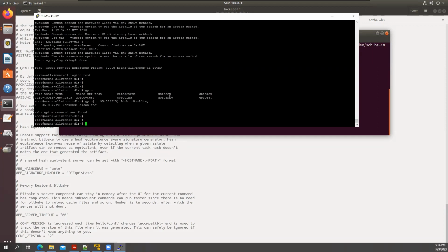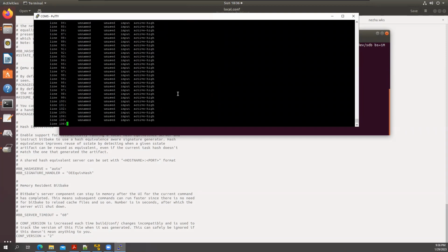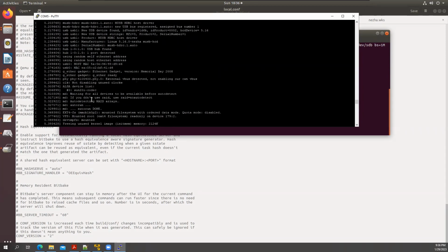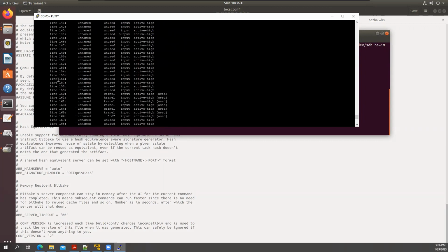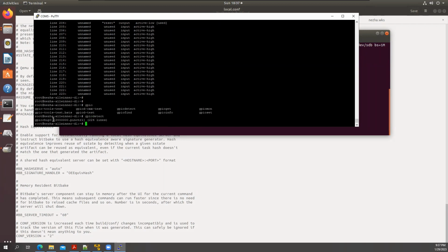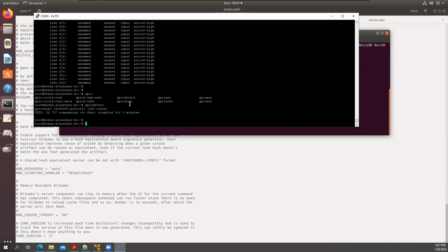So let's first use gpioinfo. So these are all the GPIOs that are connected to the main core of the CPU. All the pins and offsets are provided here. So we can use gpiodetect. It says that gpiochip0 is the only one available. That's cool.